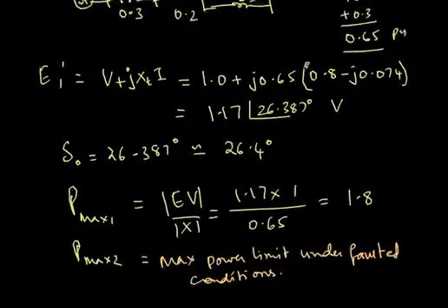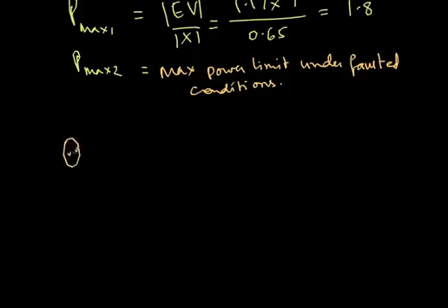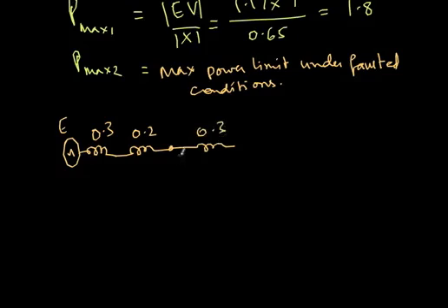So let me redraw this diagram now. I have the generator, its internal impedance is J 0.3. I'll just skip the J here, and then 0.2, and then I have one line which is 0.3, and then the other line is 0.15, and this is a midpoint, and then 0.15.